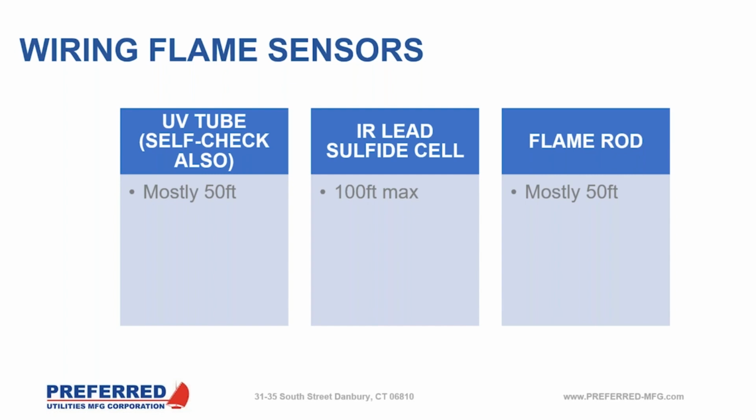The infrared lead sulfide cell, about 100 feet max on that. Again, the IR cell is a low voltage device, so keeping that shorter is always better. And again, keeping it away from any kind of other noise inducing components is very, very important. So keep those separate.